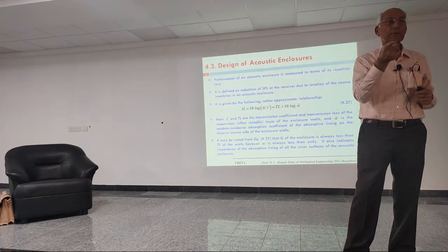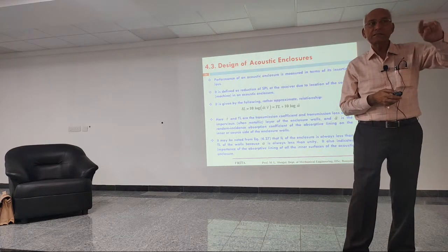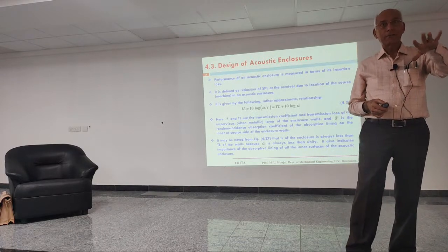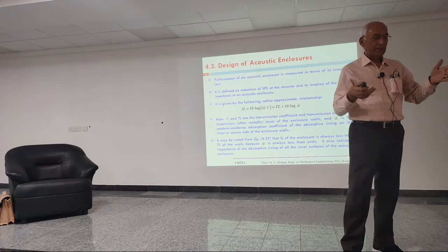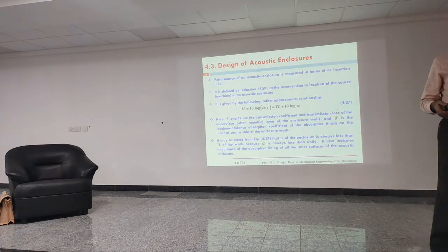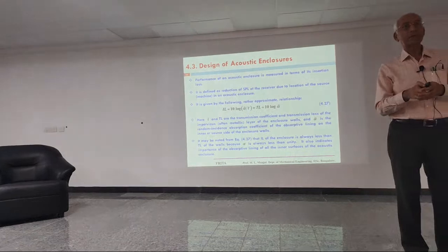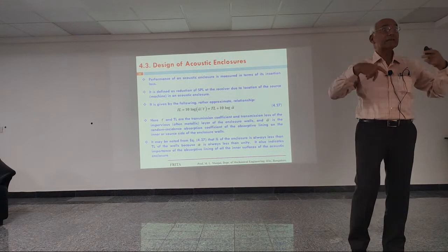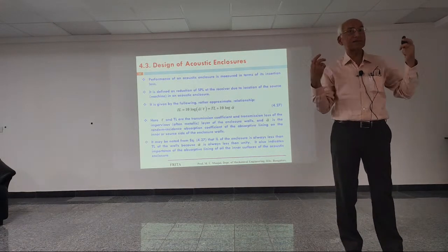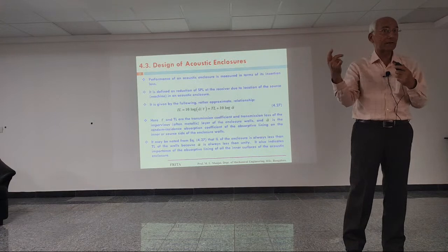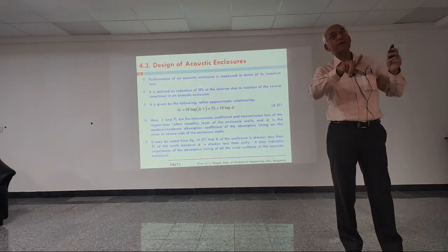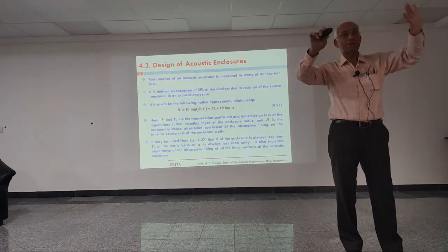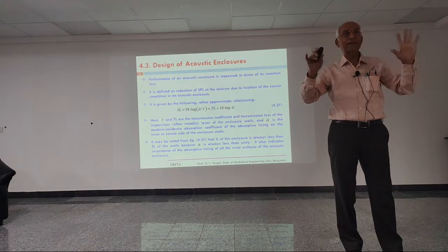And every time you cannot instantaneously change the speed of the motor. Theoretically it can be done. But when you are taking power of something like 100 kilowatts, you can't suddenly say that I don't want it and change it. And imagine, as a mechanical engineer, the loads and stresses that can happen whenever you do something suddenly. So you have to have gear systems or transmission. In fact, the biggest problem in the whole electric vehicle is the design of transmission.